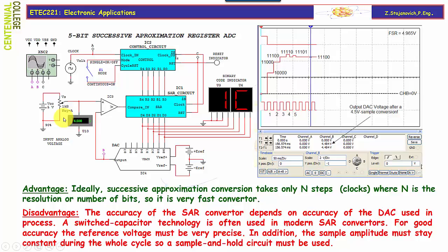The only difference is that this video covers a 5-bit resolution SAR and that the least significant bit is set up to be around 160 millivolts, as set by EREF voltage, to cover full-scale range of approximately 5 volts. It is set up in such a way to cover the maximum amplitude of the analog input. Students are encouraged to test themselves against this simulation. Unfortunately, the actual Multisim file is not available to students, mainly due to extensive abuse of the circuitry, which usually causes the simulation to crash or not to work.